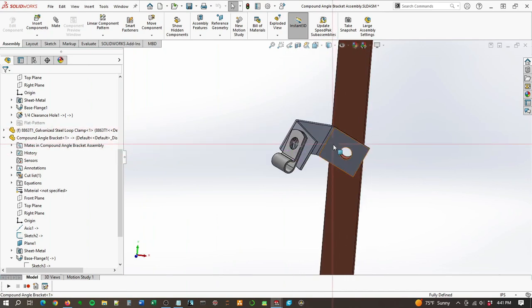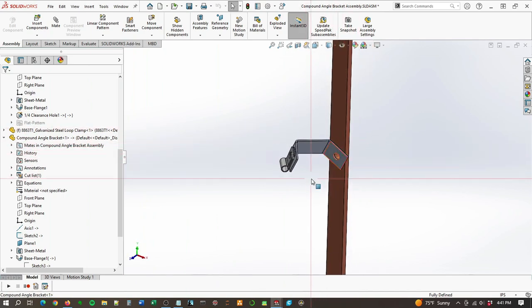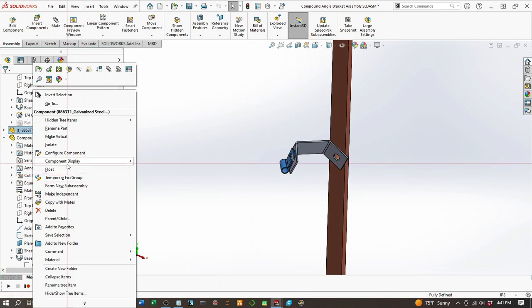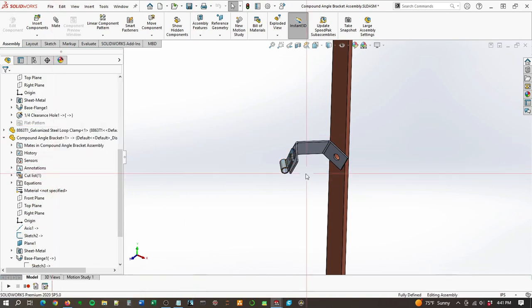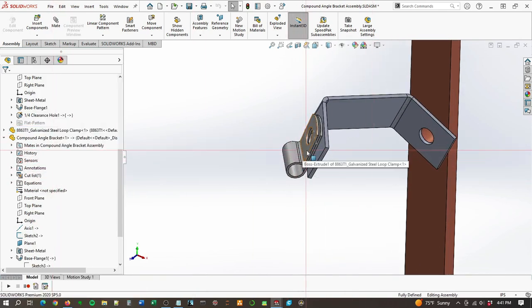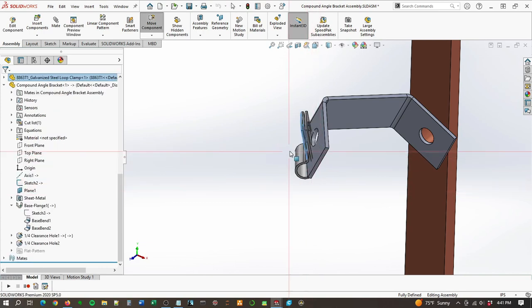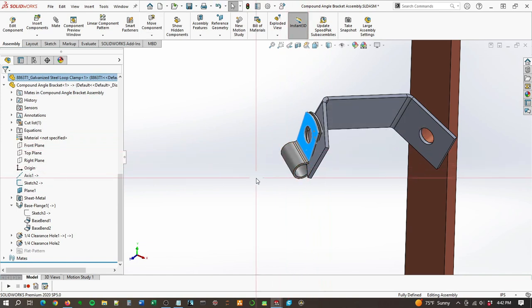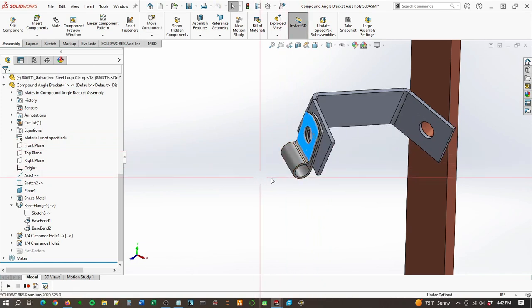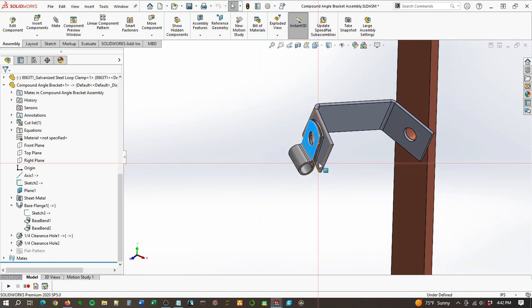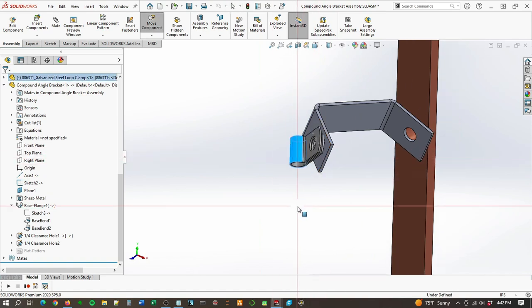And I want to show you something interesting about this. The question is, what would happen if we change the orientation of that clamp or positioning of it? But in order to test that, I had to set that clamp to a floated position instead of a fixed. So I'm right-click dragging and kind of moving it around to test the change in bracket geometry. And notice how it updated. Okay, it was pretty clean that time around.